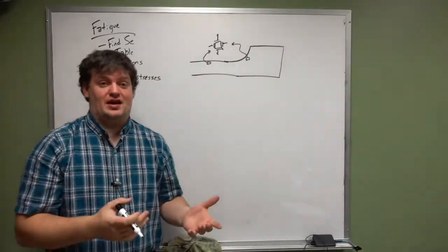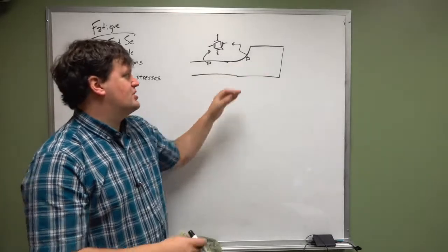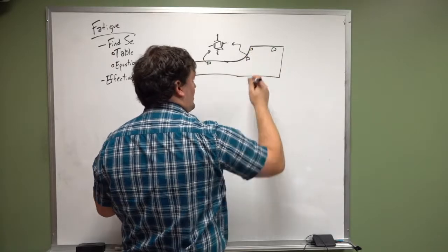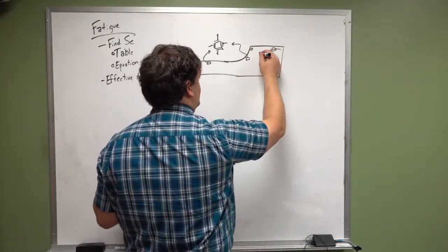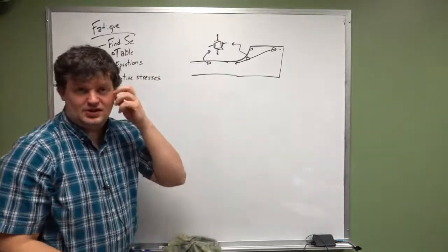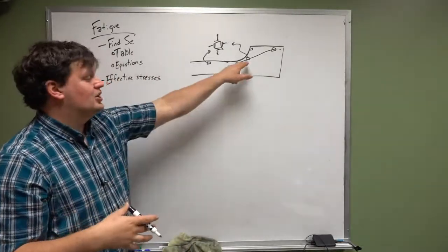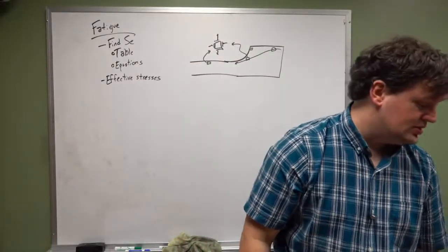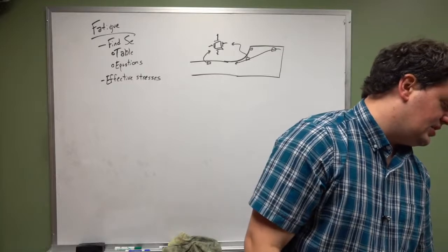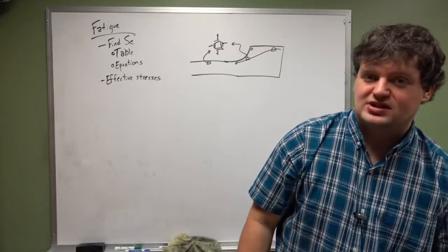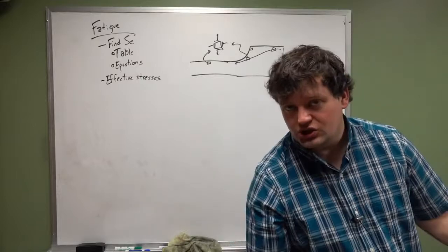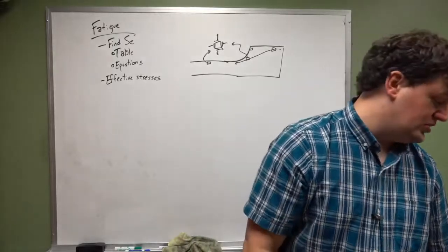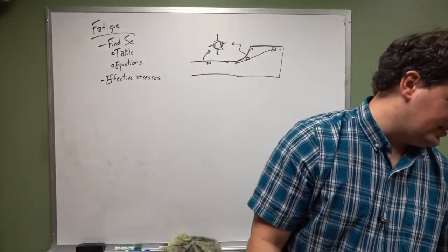It's actually greater than, because it's a transition period between over here where you have some amount of stress and right here where you have almost no stress, because that stress is being channeled like this. All that force, all that load is being carried across the notch. Anytime you have a change in geometry, you are going to experience a change in stress values. Now, it would be easier to calculate this using SolidWorks, but in this book, we do have some assistance in trying to find those values.